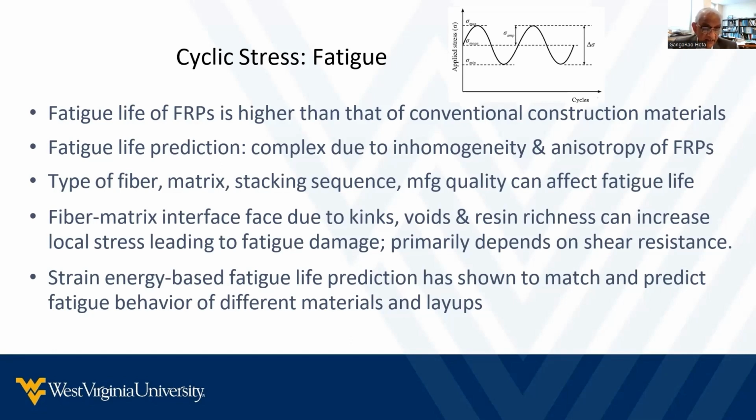However, fatigue life prediction in composites is more complex due to their anisotropy than in metals, where fatigue life prediction is somewhat empirical. Obviously, fatigue life depends on fibers, matrix, and manufacturing types. Stress risers from kinks, etc., can lower the fatigue life.